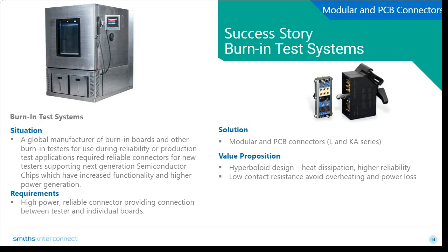So that's just a high-level overview, but essentially they have a pin side connector built into the test system itself, and each individual test board has the mating socket side. So as a new semiconductor chip is introduced, or a different printed circuit board needs to be created for it, those socket side connectors are placed on those boards and they plug right into their existing system.